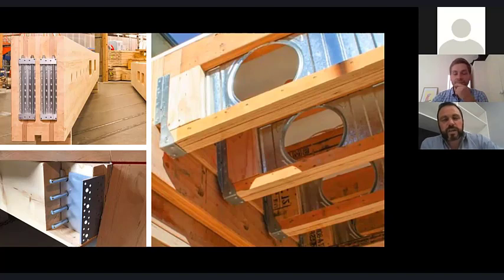Yeah, and it's linking it to the hotel that if we are going down that post and beam, you need to consider these connections. What are they? How do they work? How are they fire rated? Are they tested? And then you've also got the floor cassette. So that's a tech beam floor cassette that was used at that Australand project. And there's connection requirements there as well. But most of these lightweight systems are cladded with fire-rated plasterboard on site. And then your connections are encapsulated within that fire-rated plasterboard. So it really can simplify.